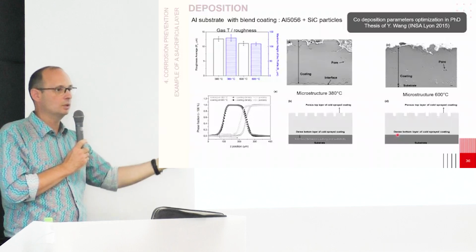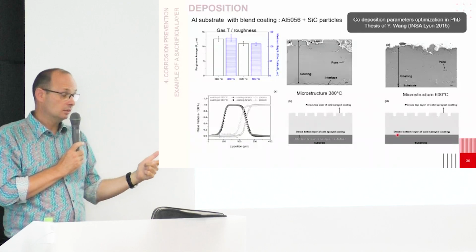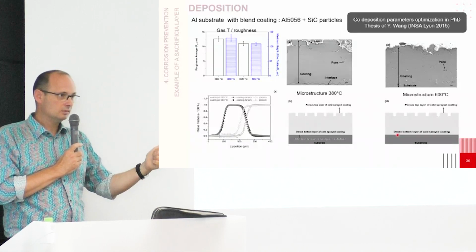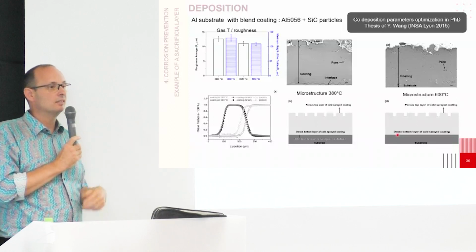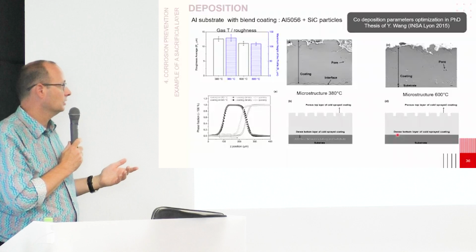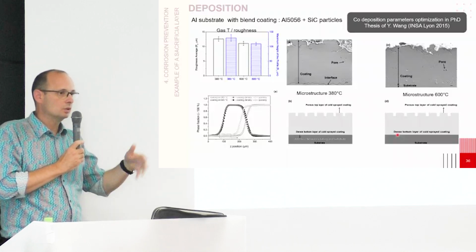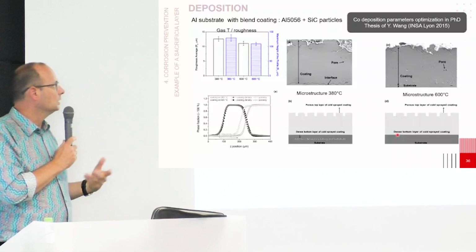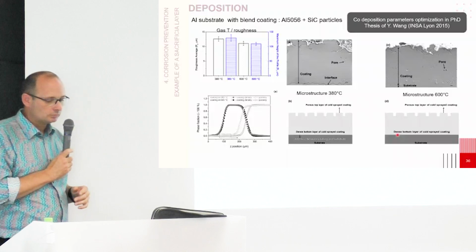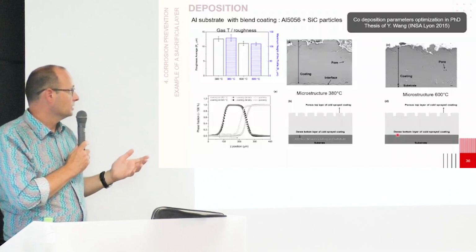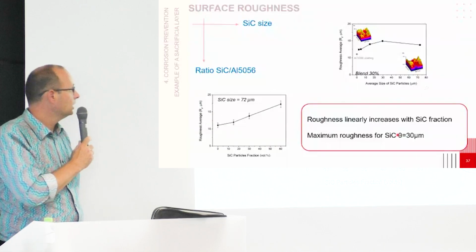Okay, thick, it will remain longer in the solution. I said what? Thick, dense, and less porous, they are mostly the same. That means that I have less defect in the volume of the coating, so the diffusion of water through this coating will take more time. There are a lot of physical characterizations that we can do to describe the coating. I will not go into detail.